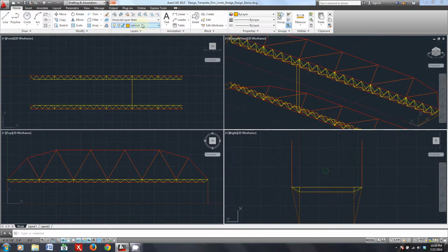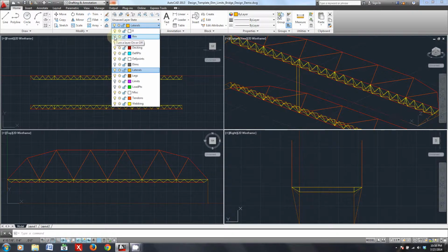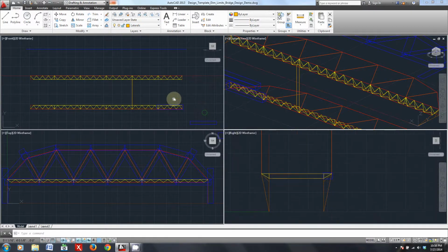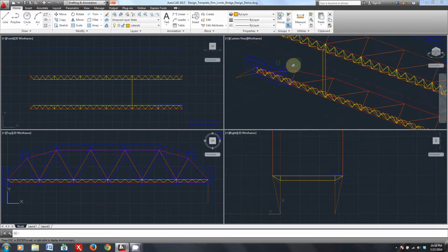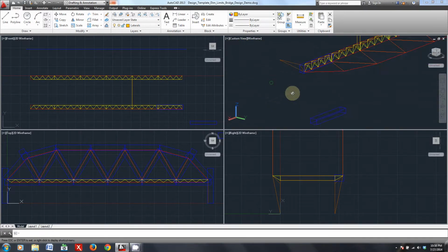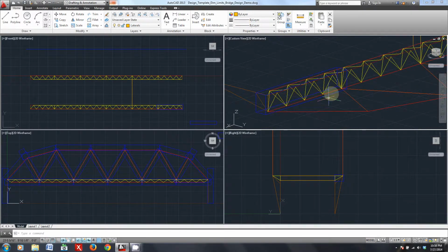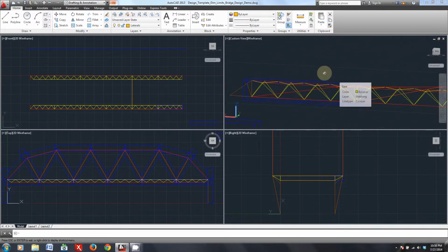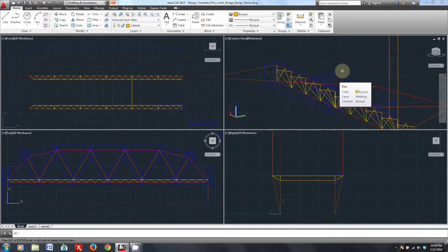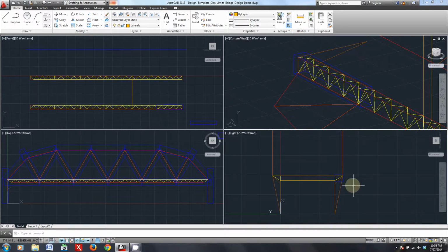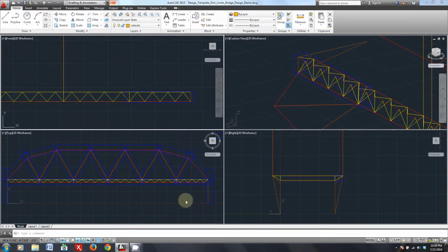And on that topic, I'll take a look at the extension of the concept of our box. I've already created a 3-dimensional box here, and the concept of the 3D box is no different from the 2D box, except I've drawn it out in 3D. Of course it's 3 feet by 6 inches by 4 inches, and just to give an example, I've enveloped it around this particular girder part, and as you can see, it fits quite snugly in that little box. Likewise, having the box in 3D and then moving it wherever you like, it'll show up on your drawing in each viewport. So very handy.